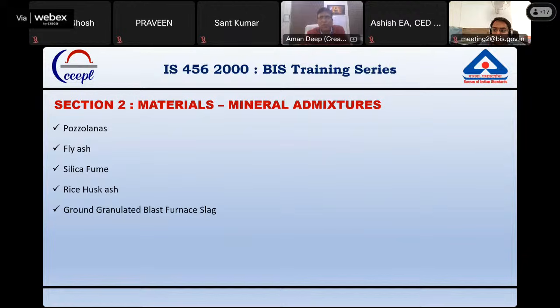So even if you are not using OPC to the full extent, suppose in one mix design you are using 400 kg of OPC, and in another design you are using 300 kg of OPC and 100 kg of mineral admixture. In a way, we can say that in both designs we have 400 kg of binding material. In the first case, OPC is the full 400 kg, and in the other case, OPC is 300 kg and 100 kg is the mineral admixture, which acts as a binder in the concrete.